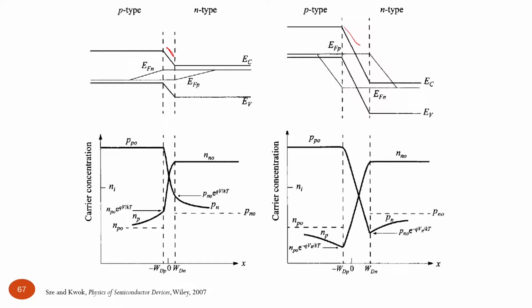You keep it linear, and what really matters is this shift for forward and reverse bias with the resultant potential barrier for charge carriers, and not really what is going on inside in terms of potential distribution, because in any case we have a strong electric field, and charge carriers inside the depletion region will be quite efficiently extracted.